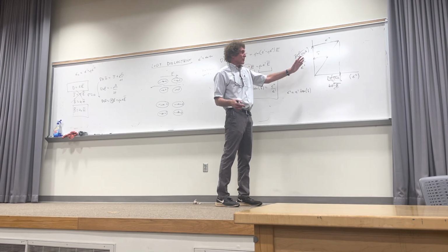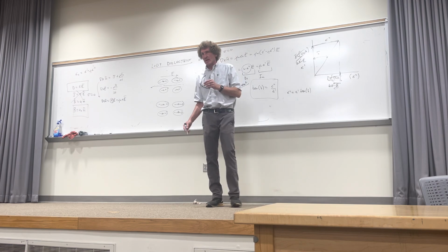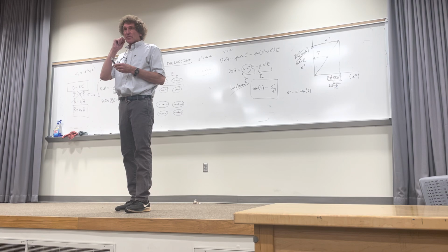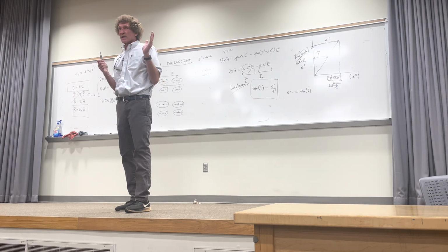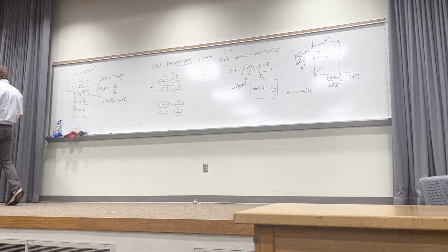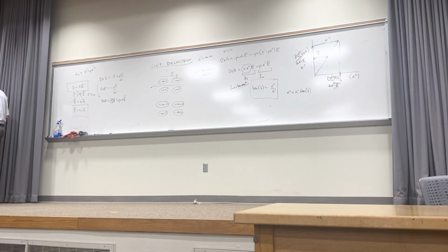I'm just going to tell you that this value for the loss tangent will vary a great deal versus frequency. The loss tangent at 1 megahertz may be very low, but the loss tangent at 1 gigahertz may be very large for the same material. So please just remember that. It varies wildly. I'm just trying to give you some insight into this. Okay. So that's really, in a nutshell, how you deal with lossy dielectric materials in terms of basic understanding. And I can tell you, the problems in his book about this are trivial.